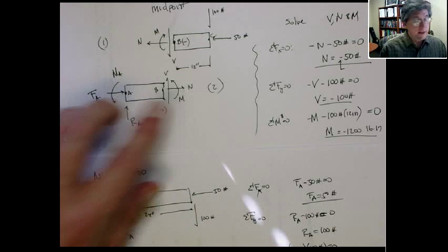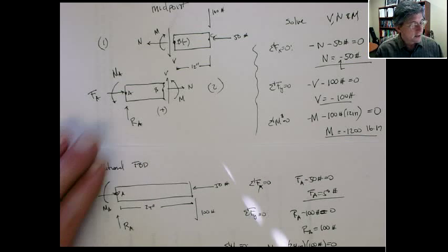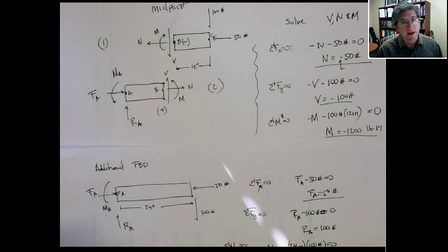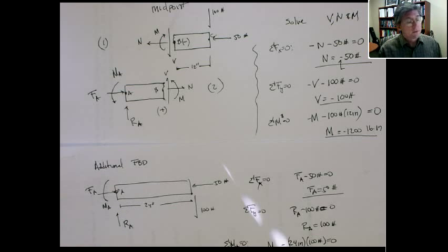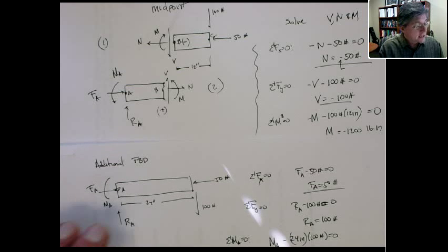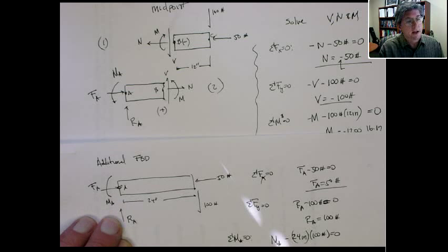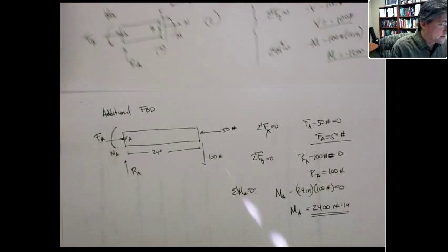to solve for M, V, and N. All right? So you have to do this additional step because you have to get the external reaction forces that exist in the body. So whenever you have external reaction forces on your free body diagram that you're going to use to compute the internal reaction forces, you very likely will have to use an additional free body diagram of the entire system or some other subsystem, some other cut, to give you the external reaction forces. Now, practice will let you see what are judicious free body diagrams to draw that allow you to compute the quantities that you desire more readily. It just comes with practice.